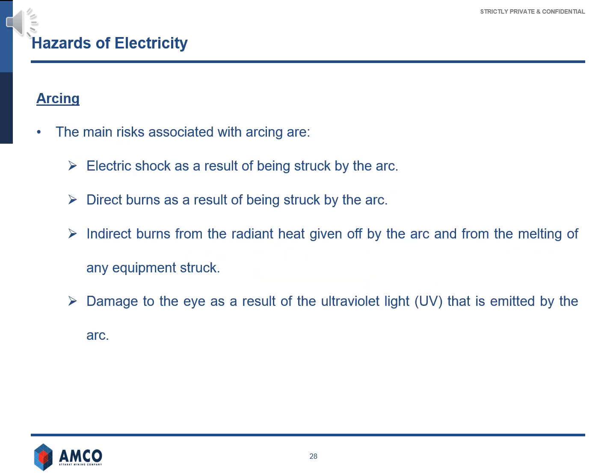The main risks associated with arcing are electric shock as a result of being struck by the arc, direct burns as a result of being struck by the arc, and indirect burns from the radiant heat given off by the arc and from the melting of any equipment struck.